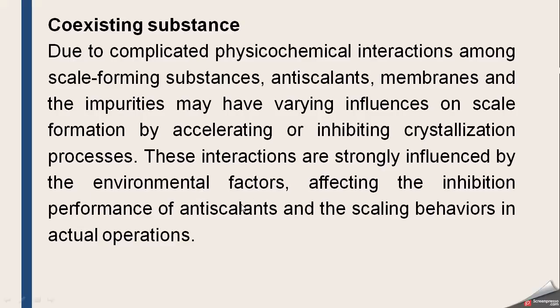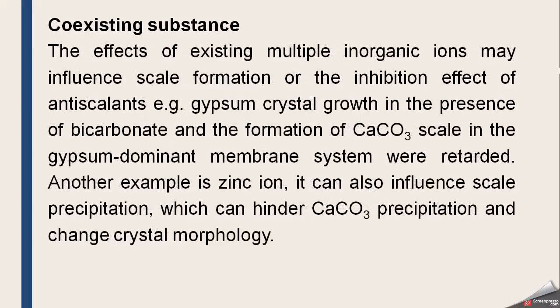So these interactions are strongly influenced by environmental factors, affecting the inhibition performance of antiscalant and scaling behavior in actual operation. That's why we perform some tests which come under the heading of static or dynamic tests, and we check the presence of many coexisting substances and check which antiscalant or which dose of the antiscalant will be better or more convenient to control the scale. So the effect of existing multiple inorganic ions may influence scale formation or inhibition by the antiscalant.